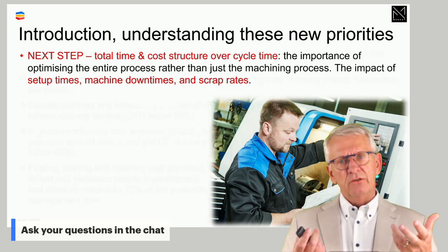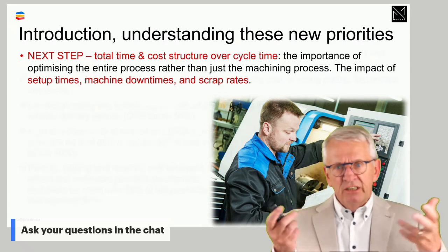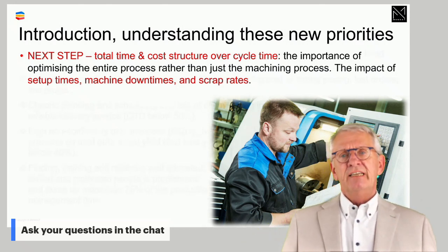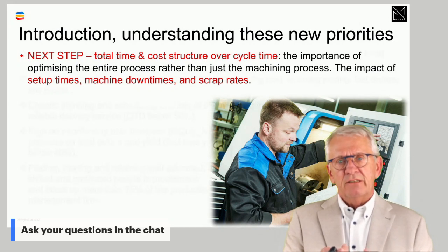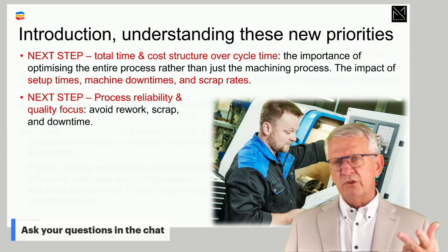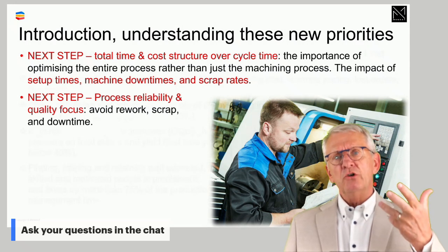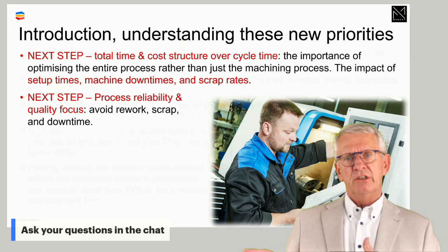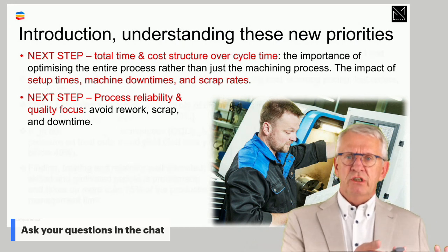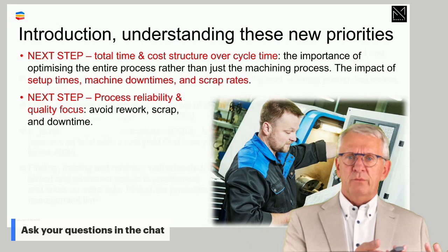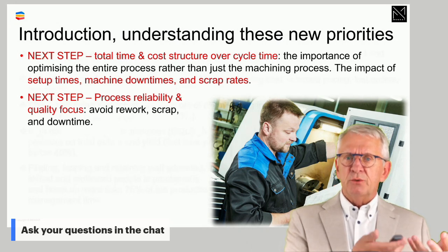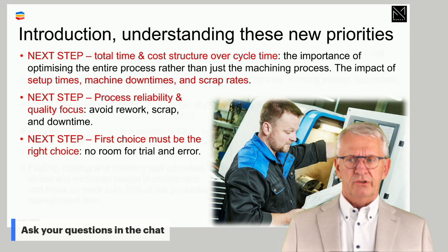That means that evaluating a situation, it's not only are the chips good and do we have vibrations? Yes, no, but it's also about did we minimize setup times? Did we try to avoid too much machine downtimes? Did we make sure that the first part is right, or are we scrapping a lot of workpieces? And setup times and downtimes, problem solving times, scrapped workpieces, in the majority of cases, point back to the machining process where something was not in balance. And that means that a balanced machining process, which is not the same as a high-performing machining process, but a well-balanced machining process, reliable, delivering the quality which is needed, predictable, controllable, that is what is most important here.